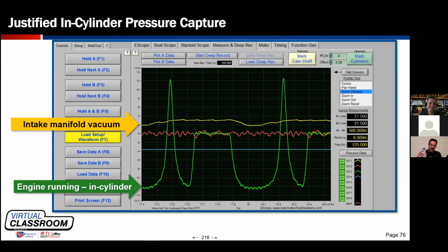But since my exhaust valve is open and the piston starts to descend, I close the exhaust valve. I should be on my induction stroke, but I can't get any air in. I go back up on compression and I build about 12 PSI right there. And the other thing, the giant curve there is a big indicator. It's usually obvious once you get some experience, but maybe early on you forgot what we talked about, that big old curve.